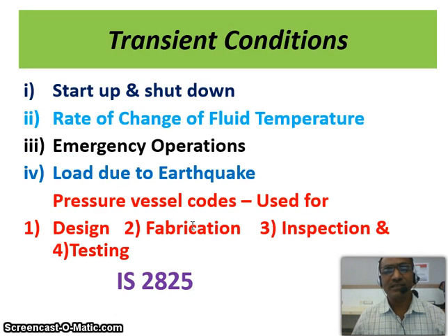Under the transient conditions, the loading pattern consists of the startup and shutdown loading of the vessels, rate of change of fluid temperatures, some emergency operations which are required to be carried out, and possible load of the earthquake if the equipment is located in an earthquake prone area.